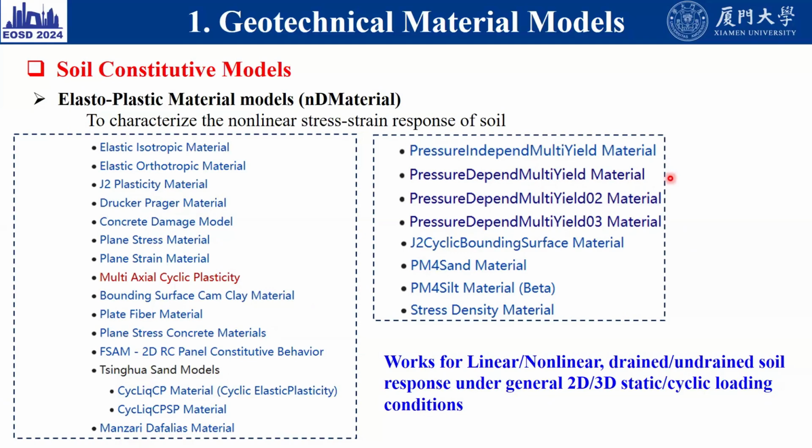And you also have PM4 Sand and PM4 Silt. Those two materials are very popular right now in FLAC. You might also know the stress density material, developed by Professor Cubrinovski and Professor Ishihara from Japan. All these materials work for linear or nonlinear, drained or undrained soil response under general 2D or 3D static or dynamic loading conditions.